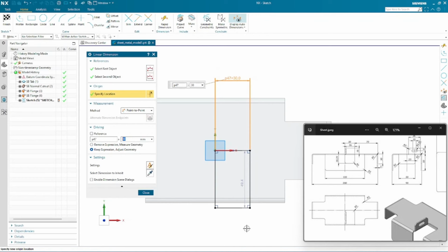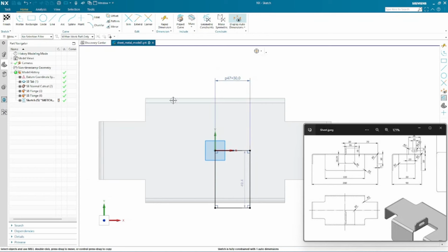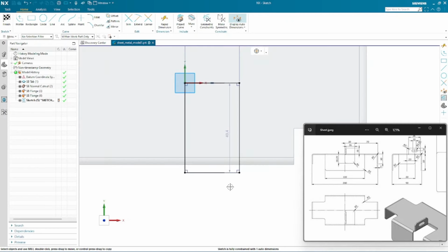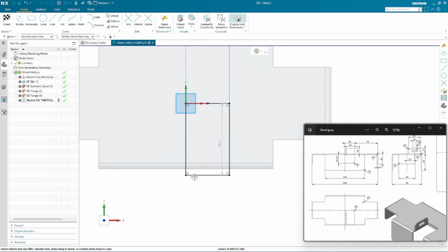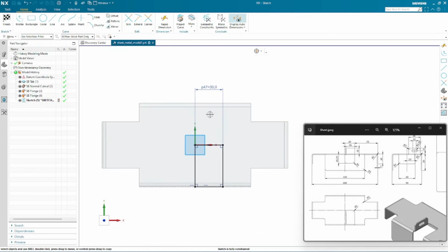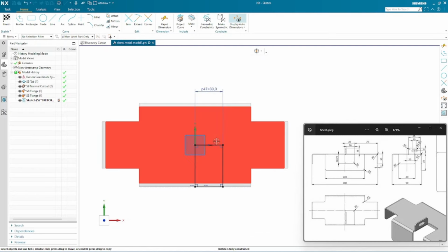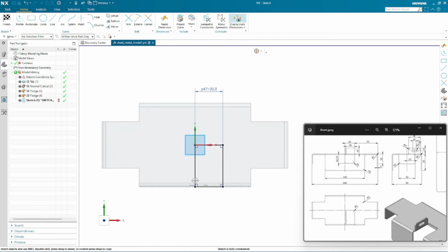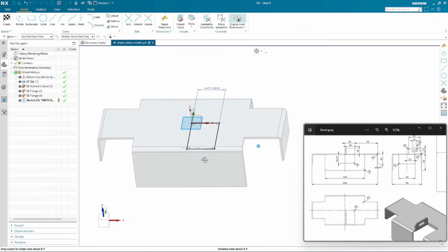and edge, it doesn't matter. Okay, in this case you can use the existing edge within work part only and use these two edges to be coincident or collinear. My sketch is fully constrained because whenever I want to create cutout, I also want to cut to this wall. That's why I use the outside edge of the wall.